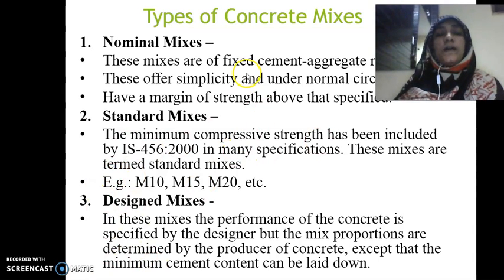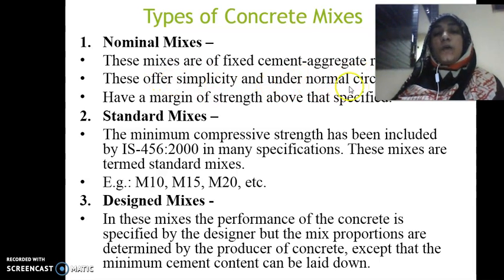These mixes are of fixed cement ratio and offer simplicity under normal conditions. Nominal mixes have a margin of strength above that specified.